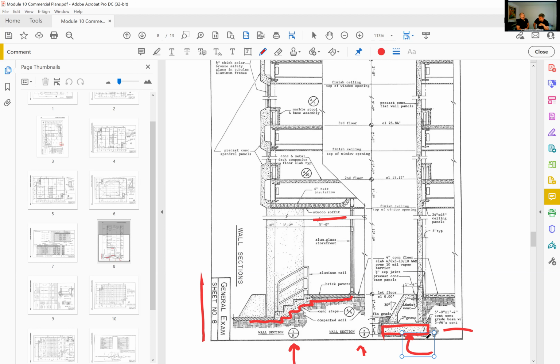That's not necessarily exam level stuff, but the size of the rebar, tell me where that comes from and how we determine that. It's right there in the note. Weren't you listening? I was not paying attention, I was daydreaming. No, it's right in the note. 5 number sixes. So remember, number 6 is the name of the size of the rebar. It's 6/8 inch diameter, and you have 5 of them.